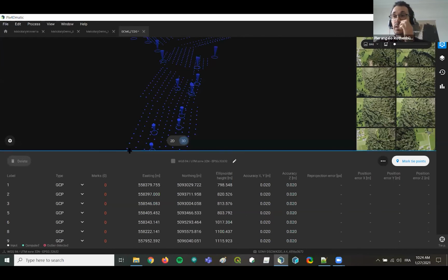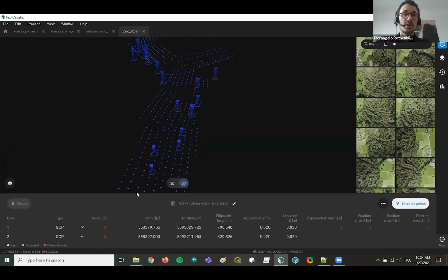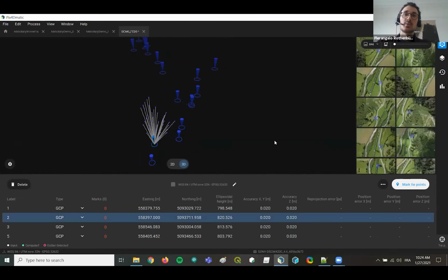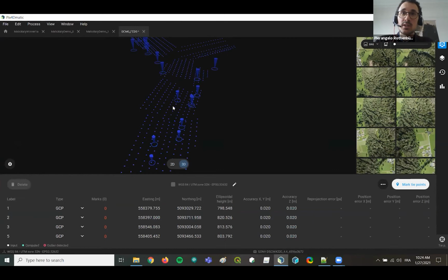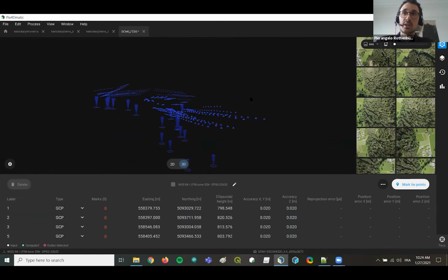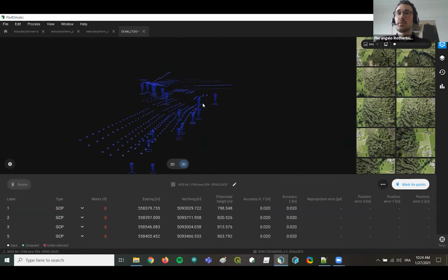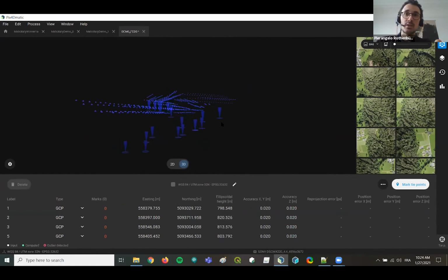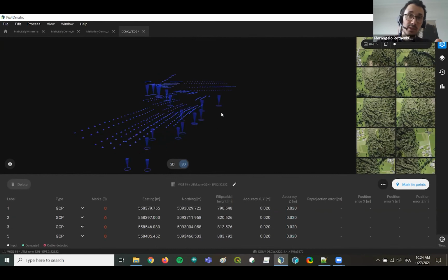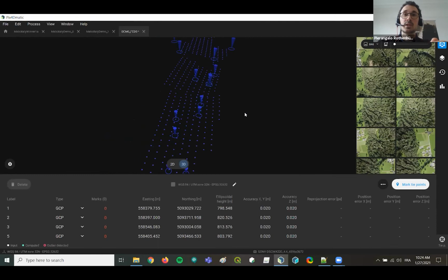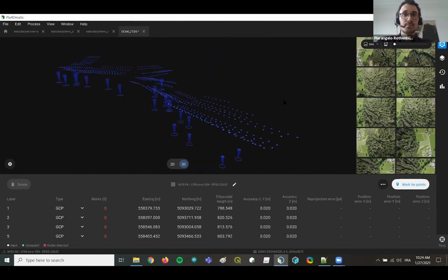Okay, so this is the tie points table. Now, something new here is that if we want to, we can already start marking before calibration. And you noticed here at the top, I can show you again, all the blue dots at the top are the images, and they're directly geolocated and displayed even if there was no processing done. So this already helps you to see if there is an issue in terms of geolocation of the images or the GCPs. So here you see it seems to make sense. They are at the same place. And so I'm confident that we can continue the project from there on.